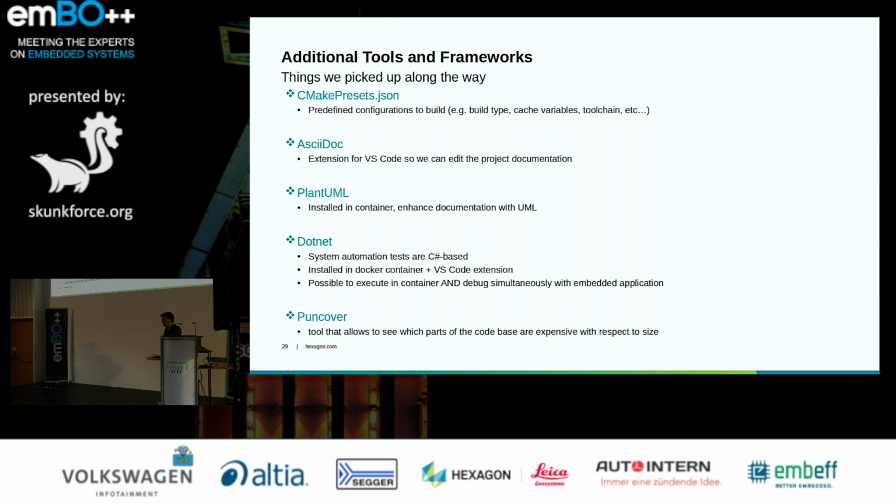The reason why we took this approach of putting everything there and trying to have a backdoor to inject a different SDK is because sometimes in the manifest, you can have tags that are not totally defined. So it could be rolling tags, referring to something that can change. And if you do west init, west update, at some point in time, maybe you cannot rebuild with exactly the same sources that you were using to build the firmware in the past.